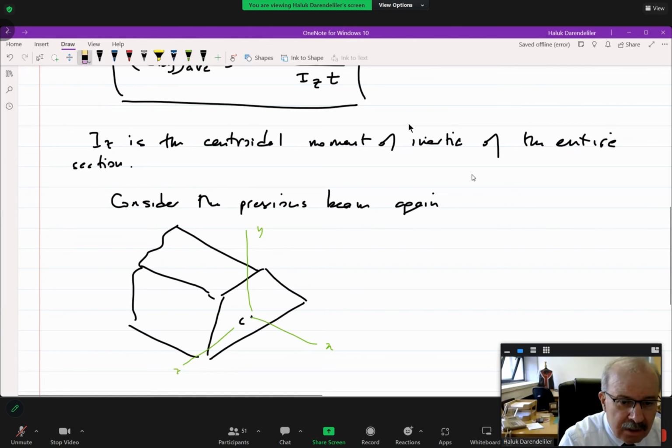And further, on the cross section, we have a shear force. Look, on this cross section, say that we have this shear force, Vy. Keep in mind that whenever we have the shear force, there always exists a moment coupled with that. Although in our book, this moment is not shown in the problems, keep in mind that this shear force is always coupled with a moment. Don't forget this. I repeat, this shear force is always coupled with the moment.